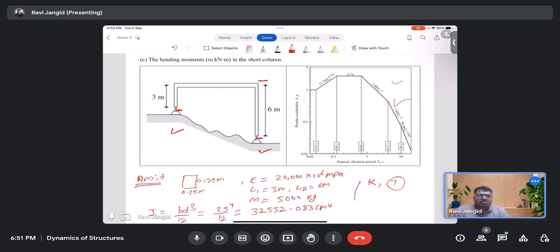You are talking about question number 4. Okay, the question is a 3 meter long vertical cantilever made of 150 steel pipe supporting a 12 kg mass. The pipe has 168 diameter, second moment of inertia, Young's modulus, and damping ratio. So in this, where is it written that you need to consider the column mass? Besides the damping ratio, mass per unit length, Young's modulus.